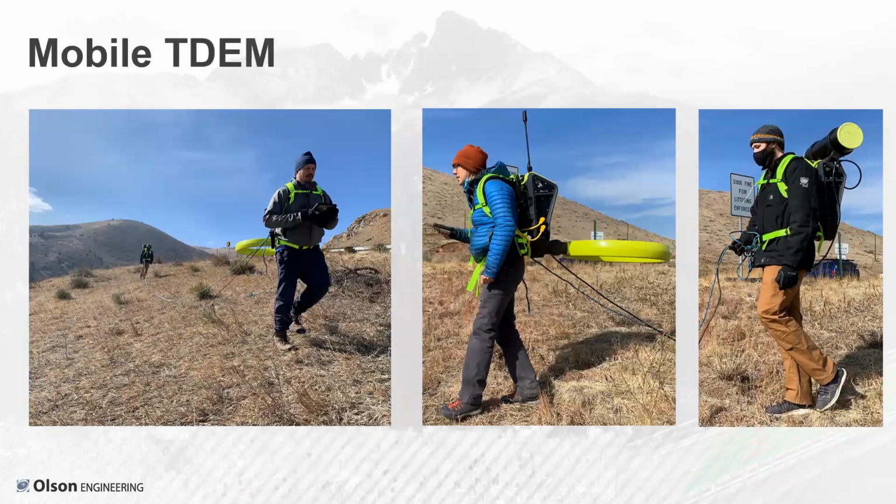Now, there's actually been some improvements in the last few years in time domain instrumentation, and now there are mobile time domain systems available. And this is a picture of us testing out the system we just got that allows us to do what I showed you a couple slides ago in terms of point measurements with time domain, but moving. So what this essentially is, the horizontal large loop there is the transmitter, and then the cylindrical object is a housing that holds 3 perpendicular receiver coils.